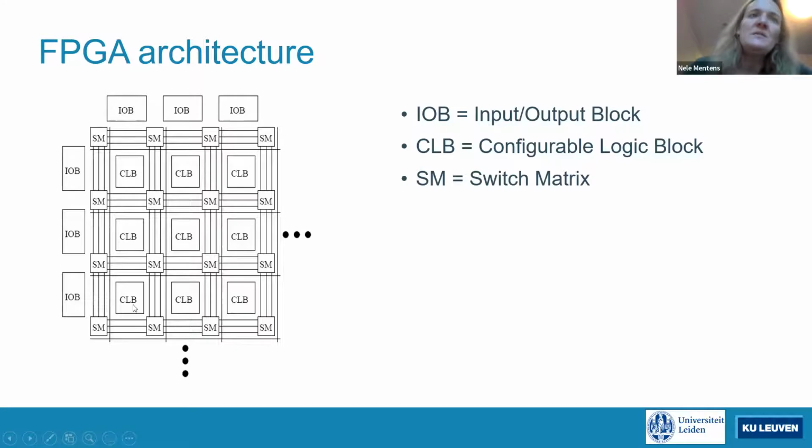In this case, what we do is we write hardware description language code that will be mounted on these CLBs, such that they can execute what needs to be executed, but all in parallel. So all the CLBs can be programmed and work in parallel. While in a CPU, you sequentially execute instructions on the CPU.